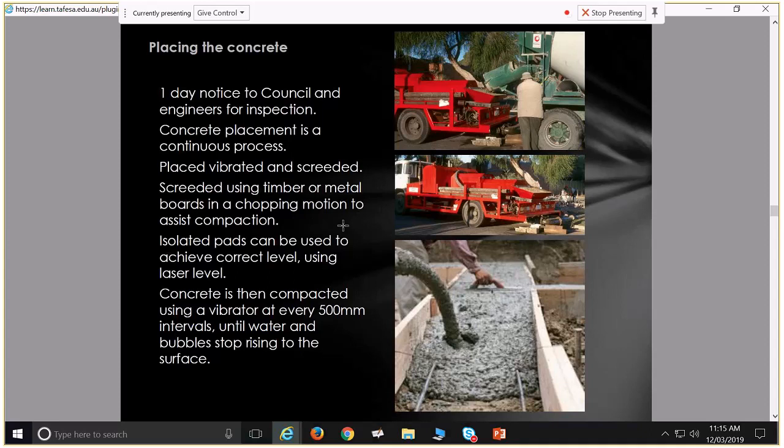work is still cool. If your steel work heats up, it expands. And then if your steel work is hot when you put the concrete in, and then it cools down from that initial contact with the concrete and it shrinks, you don't get the same bond between the concrete and the steel that you want. So it's great to start really early in the morning for that reason. It's also great because it's cooler, people can work flat out, and you're not getting concrete trucks stuck in traffic because you're doing all your stuff before that.